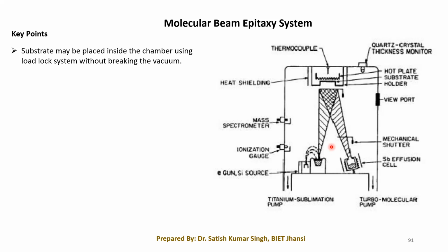A combination of other pumps, like in this case the turbomolecular pump and the titanium sublimation pump, will be used together to evacuate the chamber. Normally, achieving this ultra high vacuum takes many days. It cannot be achieved within an hour or a day. It will take a few days to evacuate a chamber and achieve the ultra high vacuum, so it takes a lot of time.